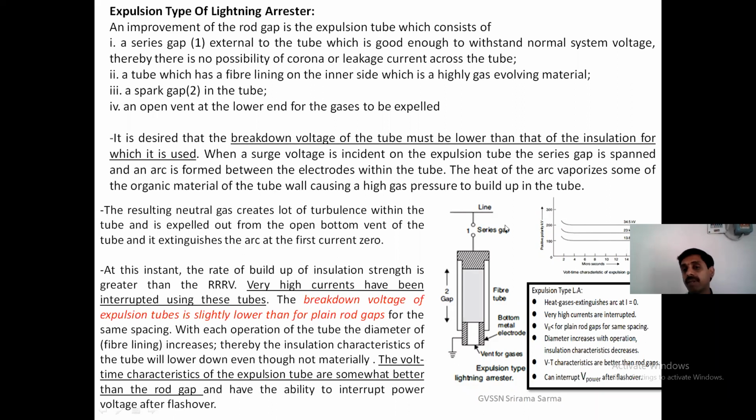With each operation, what happens? The inner lining is subjected to the arc, and it will slowly deteriorate. The diameter of this tube will increase because it is subjected to arc heating. As the diameter increases, the insulation characteristics of the tube will decrease. If you take the volt time characteristics, they are better than the rod gaps. So these expulsion